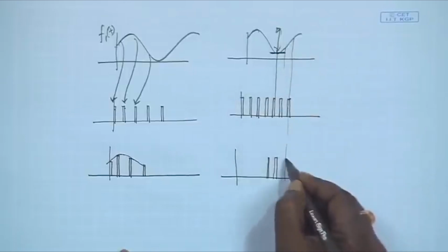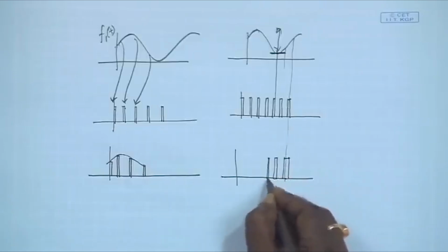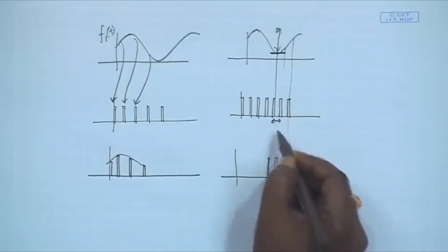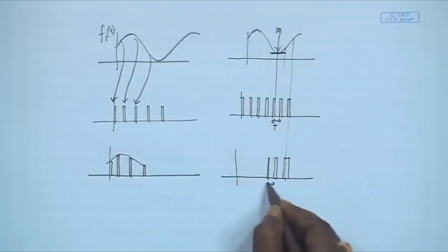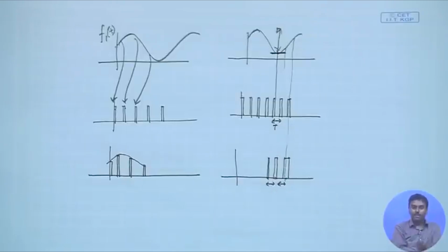Here it is increased slightly more, so here the pulse width should be more. The period or the center of this pulse should have the same frequency as this. Whatever time it has, this time the center of this pulse will have the same time, but the width of the pulse is now getting modulated according to the message signal. So basically what is happening, the pulse is being carried now, and there is a characteristic of that pulse which gives us indication about the signal.